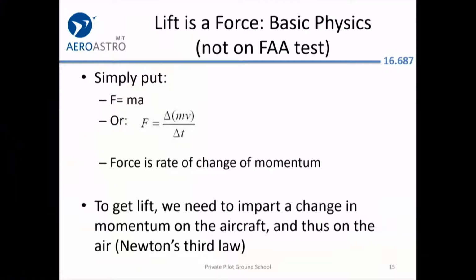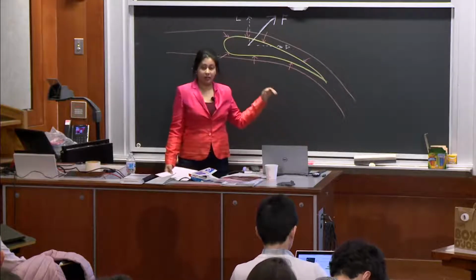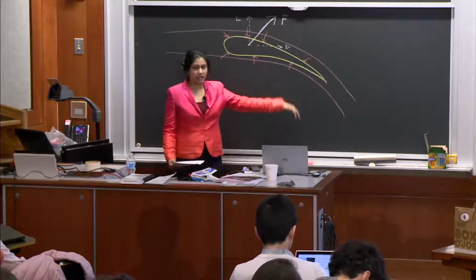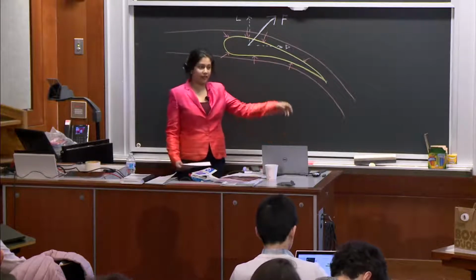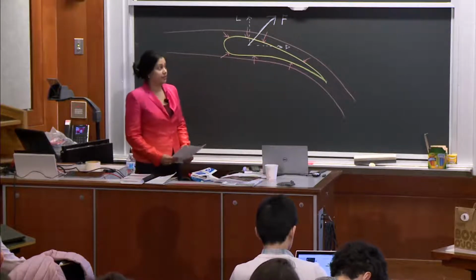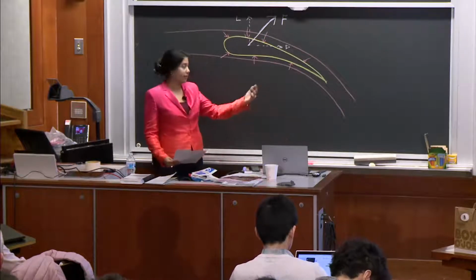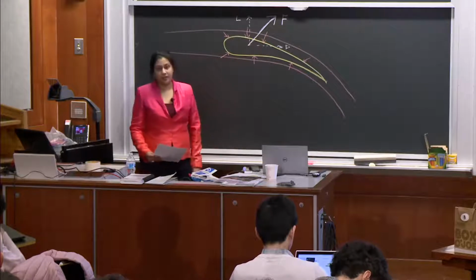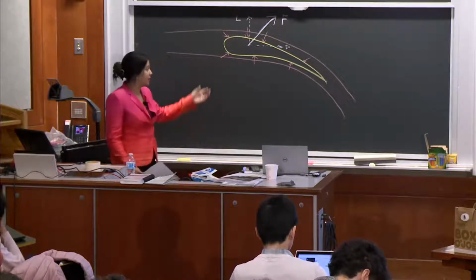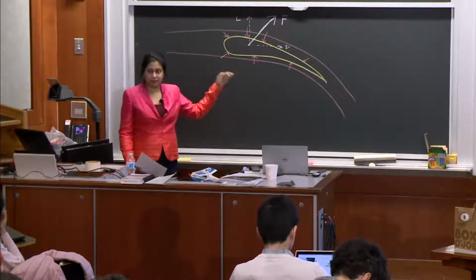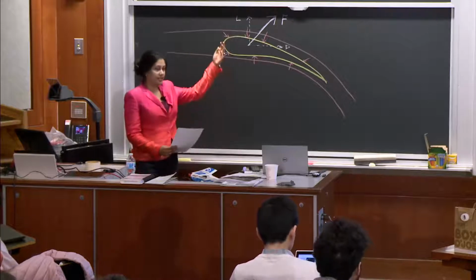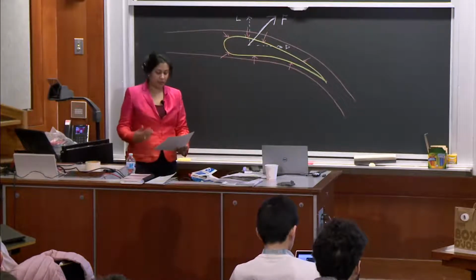In the case of an airfoil, we're changing the direction of the air. So the air has velocity, it's coming in, we're changing the direction of that air, and that's generating the lift. So because we changed the direction of the velocity, that creates a force, that's our force F. So F is actually here representing the rate of change of momentum, of us pushing those air molecules down and generating a force, creating the airfoil to be lifted up.